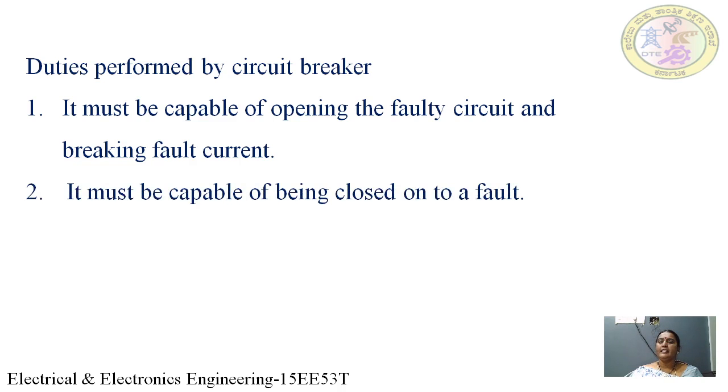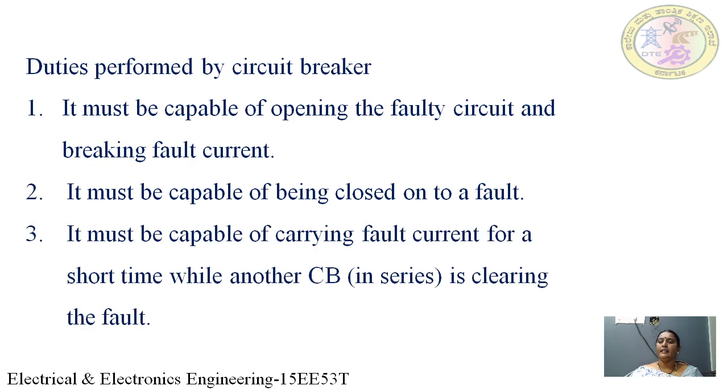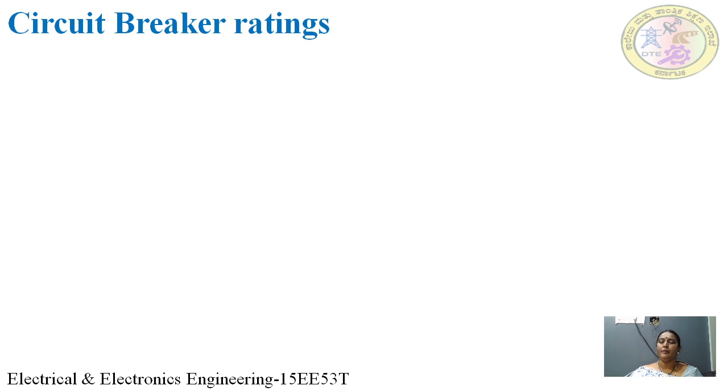And next, it must be capable of being closed onto a fault, and it must be capable of carrying a fault current for a short time while another circuit breaker is clearing a fault. This is the duty performed by a circuit breaker.